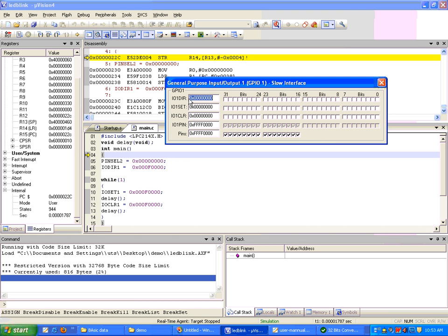And these are the different registers we use in the program. IO direction is set for whether the pins are enabled for output or input. If you configure this as 0, the pins will be configured for input. If you select 1, the pins will be output.